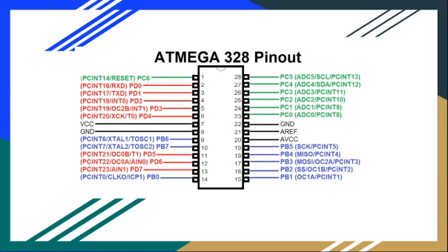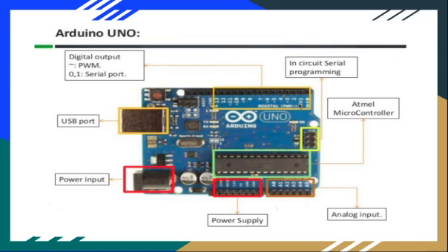Let us see the I/O port structure for Arduino in specific to that Mega 328. Here you can see that all in blues are port B, all in greens are port C, and all in reds are port D. And we can easily tell from the previous slide that PD0 to PD7, that is port D, maps to the Arduino's digital pin 0 to 7.